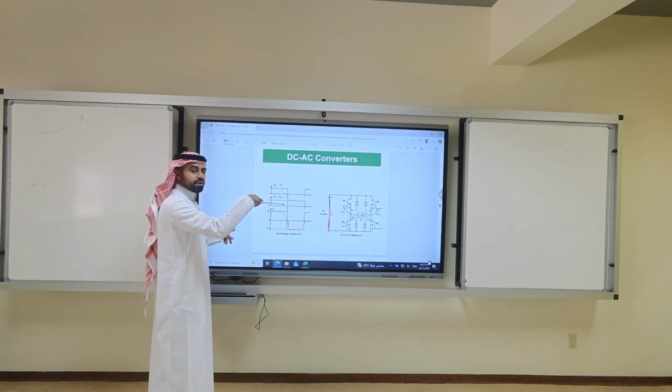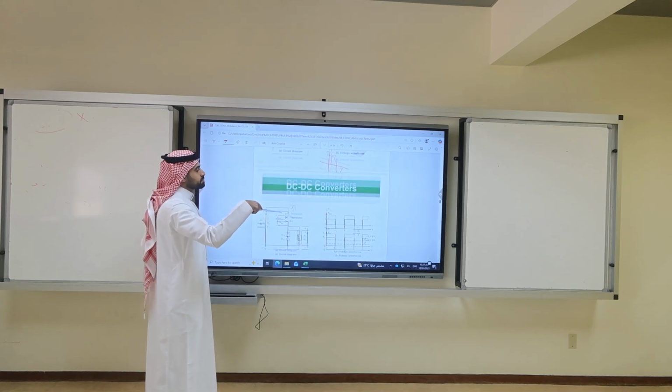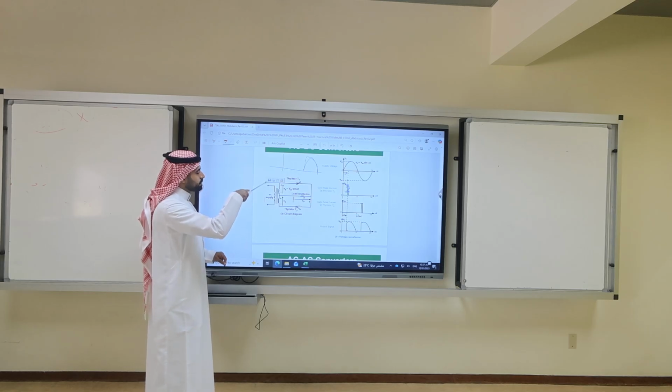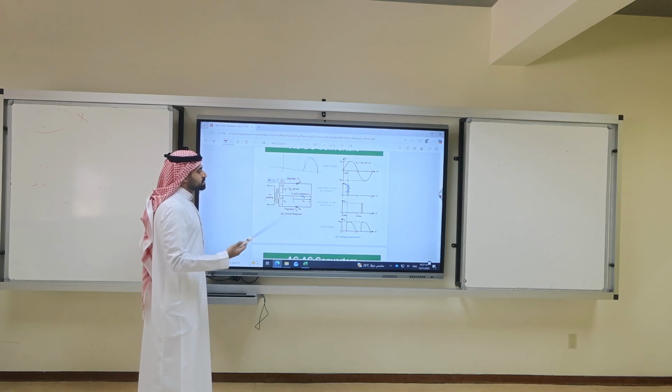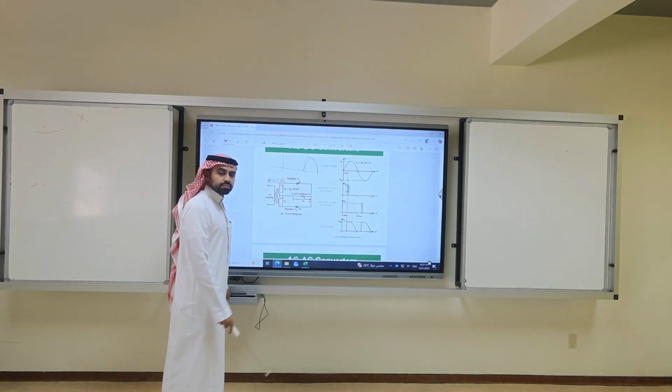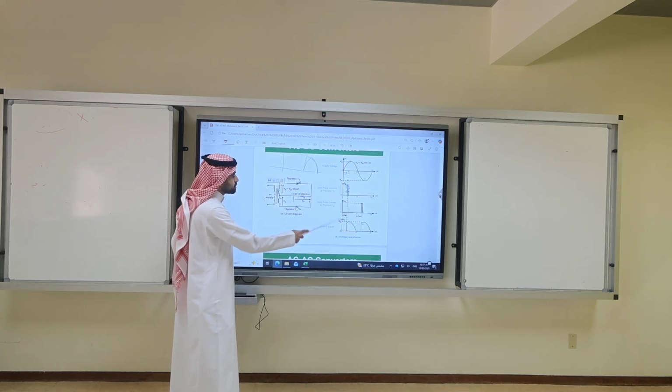These ones, the thyristor. What is my input? The AC supply. What is my power converter? It is this circuit. What is my controller? It is a thyristor firing circuit. What is my output? It is the voltage across this resistor.